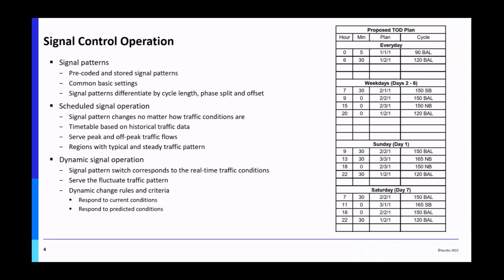Okay, so on the highway with synchronized intersections, most signal controllers store multiple timing patterns to serve different traffic conditions. The signal patterns would be switched from one to another according to certain rules. Traditionally, the pattern switch follows a pre-scheduled timetable, which is usually designed by time of the day and day of the week. This is an example of the timetable.